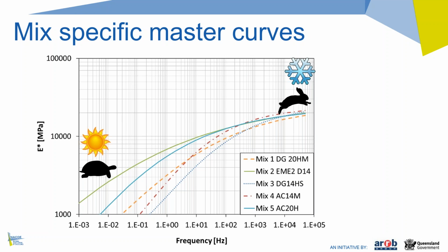So if you look at the bottom left of this slide, you will see that at 1000 MPa the line is drawn. That's because currently the minimum modulus that we use in mix and pavement design for asphalt is 1000 MPa, and we're not proposing to change that. If you do testing in the laboratory, you will get values below 1000 MPa. I hope that answers the question.